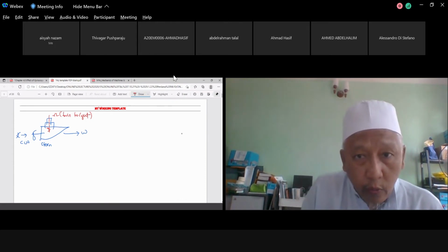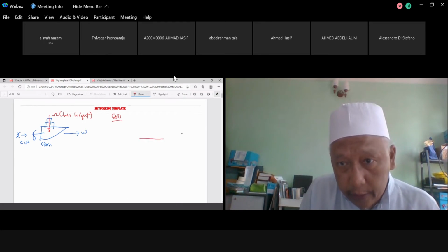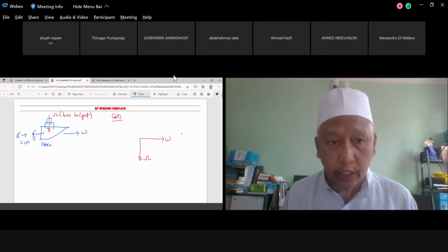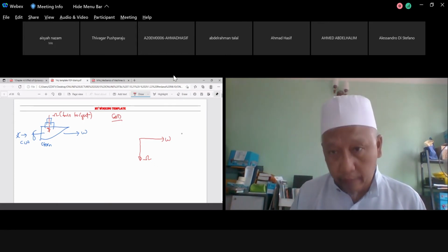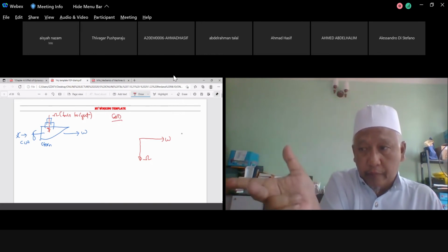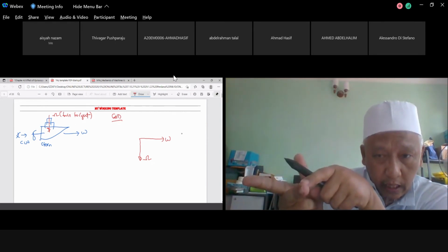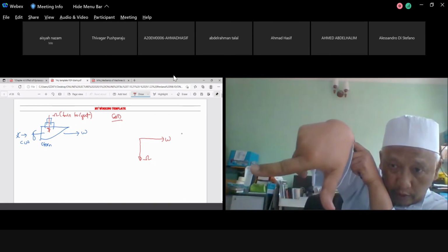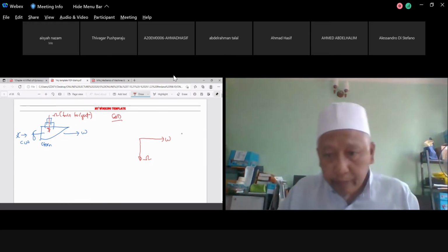When you construct the gyroscopic vector diagram, you'll get the omega, the spin velocity, and the precession velocity, and you have two choices. Either construct it in 2D or 3D, it doesn't matter. It's up to you to decide which you feel is more convenient. So you use the right hand rule. To remember: this one is spin, this one is your precession, this one is your couple. Put your hand on the drawing, and you find that this one is spin, this one the precession, this one the couple.